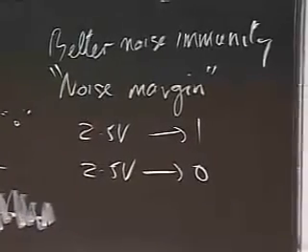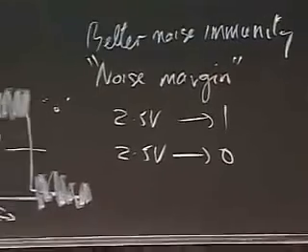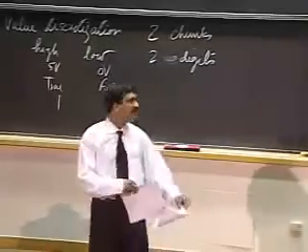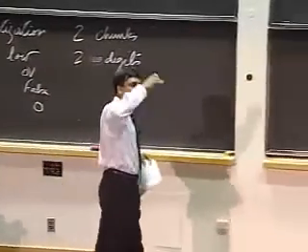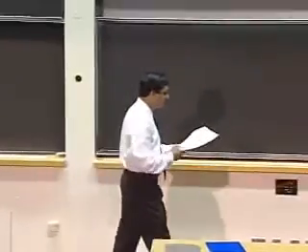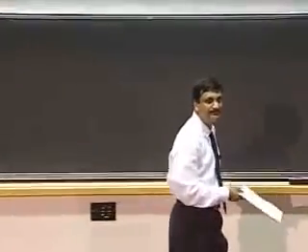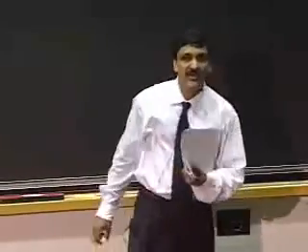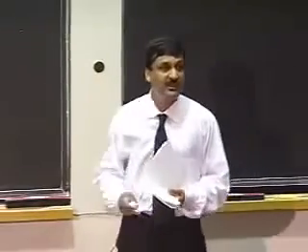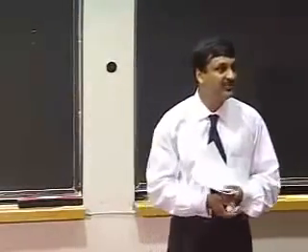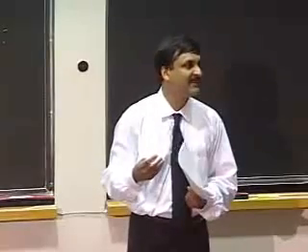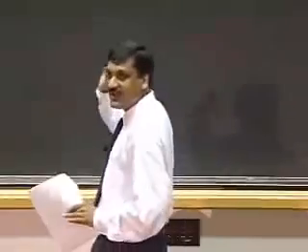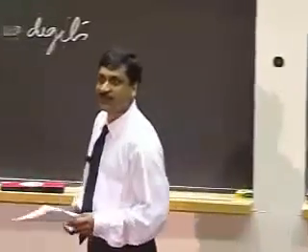So notice that I have a nice little noise margin here, which simply is the English meaning of the term. There is a margin for noise, okay? And even though I can change the signal value by up to 2.5 volts, the receiver will still correctly interpret the signal. So I decided to discretize values into highs and lows, and because of that, if all I want to do in life is send highs and lows, I can send them very effectively. There are many complications, but if all I care about is sending highs and lows, I can send them with a lot of tolerance to noise.